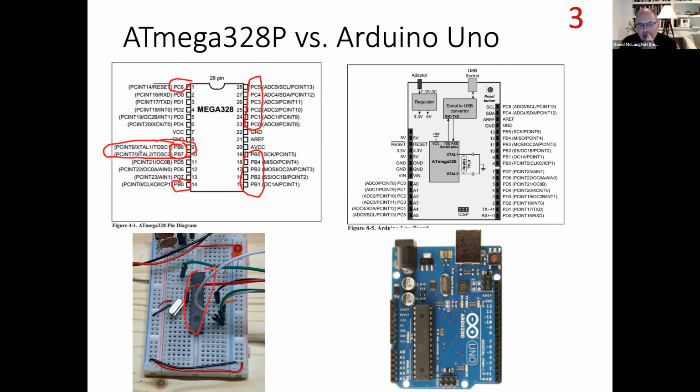So, when you look at this drawing that I'm marking up, what you can see is each pin serves multiple purposes. So let's take this pin right here, pin number 28. That pin is PC5, so that's port C pin 5. We'll talk about that in more detail. It's also ADC pin 5. It's also SCL, and it's PCINT13. It can be configured for all of these purposes. So these various pins do multiple things. Right now, we're focusing on their use for general purpose input output. So we have port B, port C, and there's also port D, 0 through 4 here, and then 5, 6, 7 here. Okay, so we just sort of chase them around.